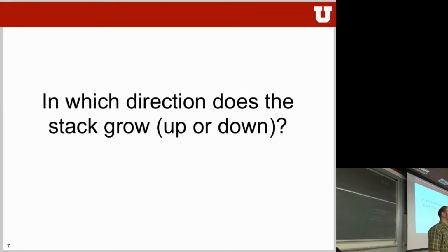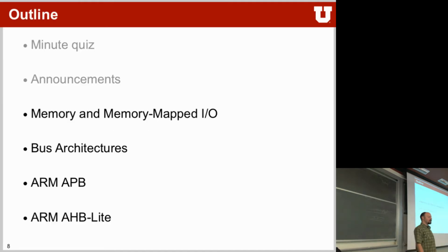When would you want to change the linker script? I would think it's something like when you're writing the BSP or something on the code, right? It's not very often that we need to. Yes. No, usually you don't need to touch the linker script, especially not if you get an environment for a microcontroller that's already set up. But sometimes if you start a new environment or a new project or a new platform, you have to write the linker script yourself. What you oftentimes can do is take somebody else's linker script and change it the way you need it.